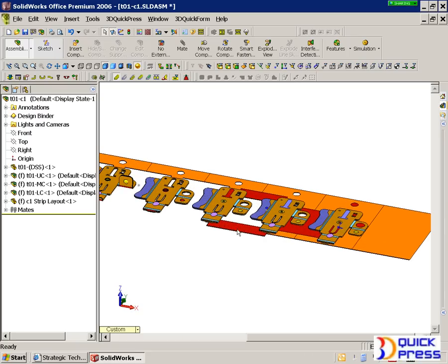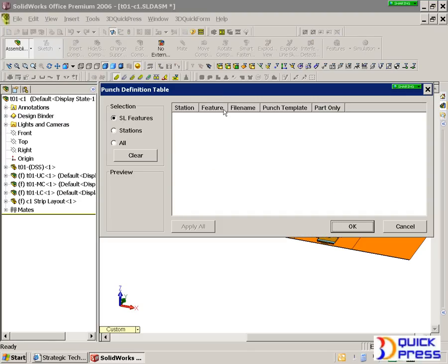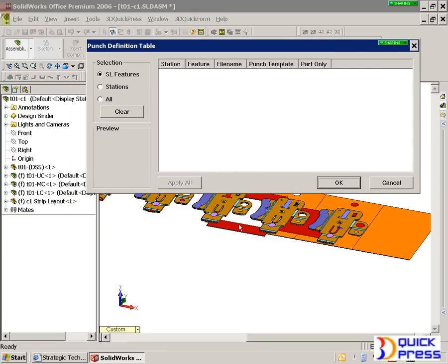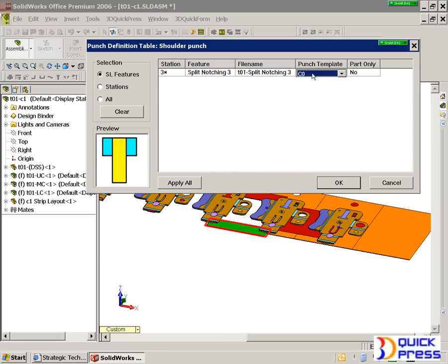Let's get started with tailoring some of the cutting punches. I'm going to pick this cutting punch right here, and I'm going to go into setup of the punch itself. I could tell it to be any type of retaining method, and these are customizable. I can tell it to use the system template, which is whatever I want as the default. As you can see here, we have many different styles, and there's no limitation on the amount of styles you can have because these can be defined by you.